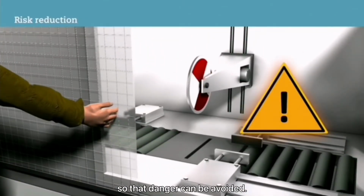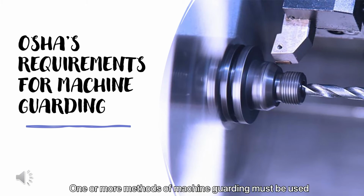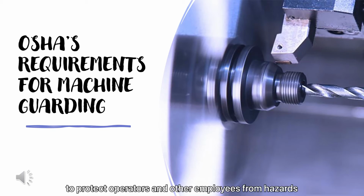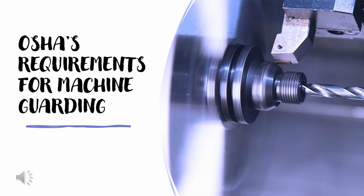danger can be avoided. The general requirements according to OSHA state that one or more methods of machine guarding must be used to protect operators and other employees from hazards, including those created by point of operation, in running nip points, rotating parts, flying chips, and sparks.